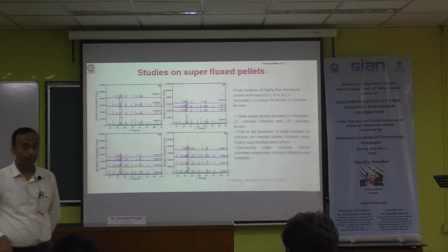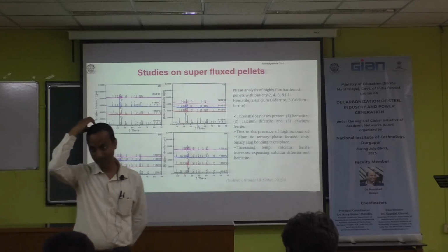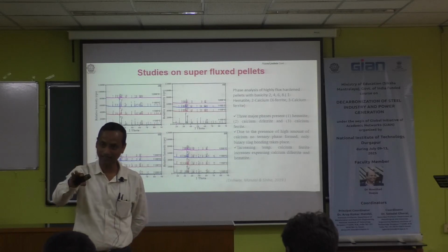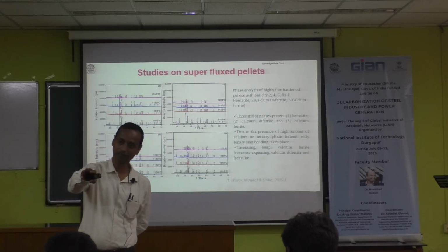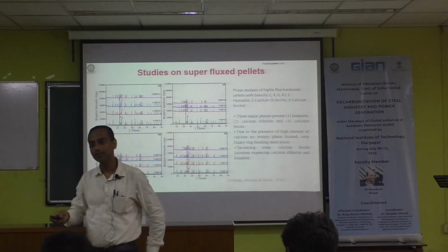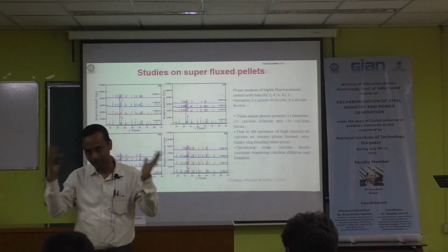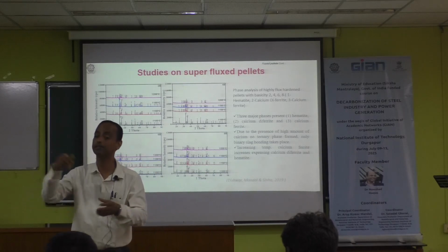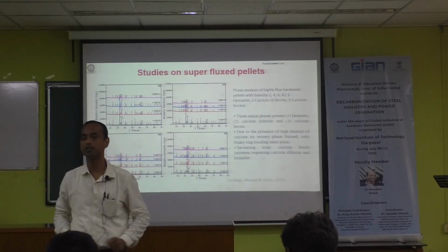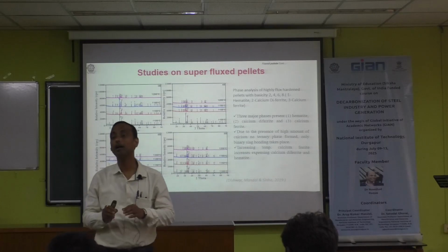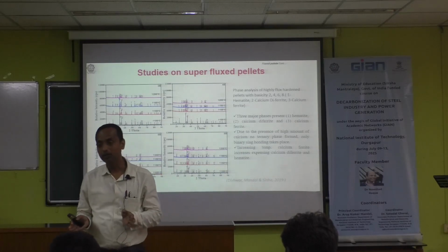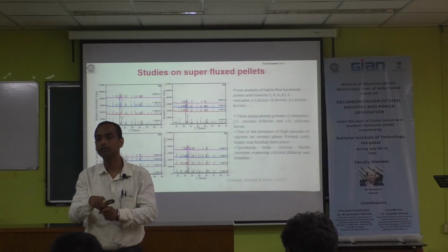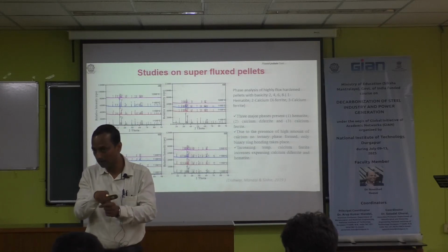Higher requirement. Now, in steel making, if your steel making operation requires lime fines, you know the problem with its hygroscopic nature; sometimes it explodes due to moisture absorption. So if you want to avoid that lime content, you can do incorporation of lime in some material so that it will not be hygroscopic.